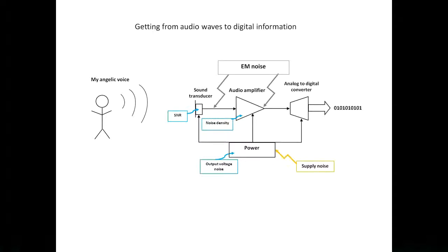Then there is the electrical noise on the supply lines, which if not filtered will be directly fed into the microphone and amplifier. It is important to mention here that if we wish to use the USB as a 5V supply, we will have a lot of headaches, since this supply is extremely noisy, and a lot of filtration will be needed. And finally, we have mechanical noise. Background noise, like my neighbors. We have vibration-based noise, like when a truck is passing in front of my window, and reflections, echoes of the primary sound I wish to record.